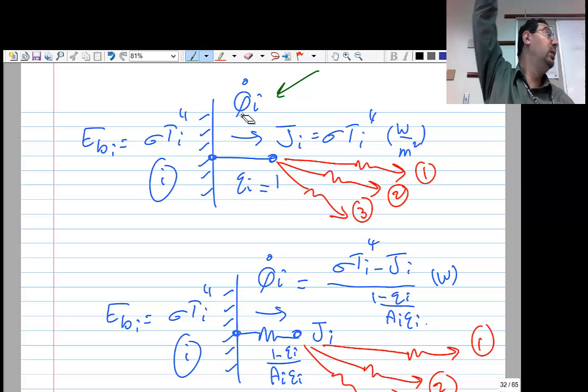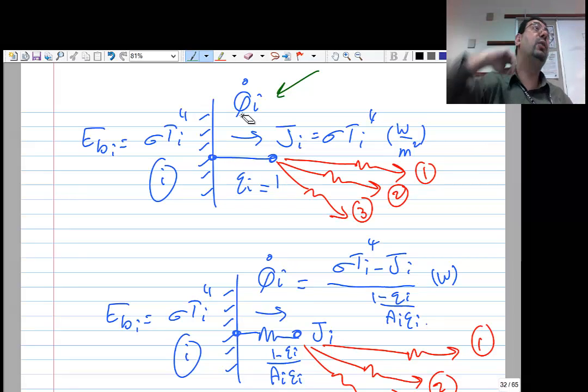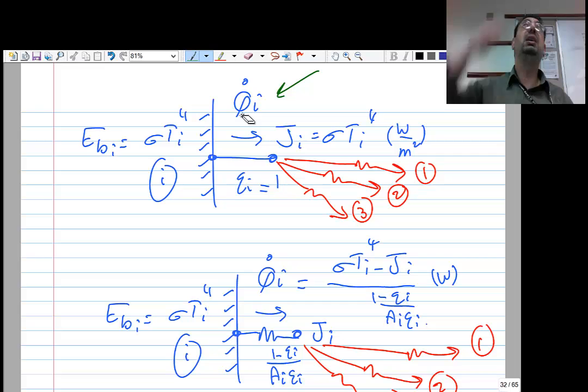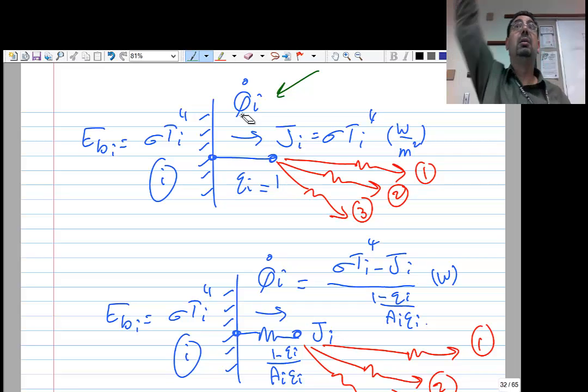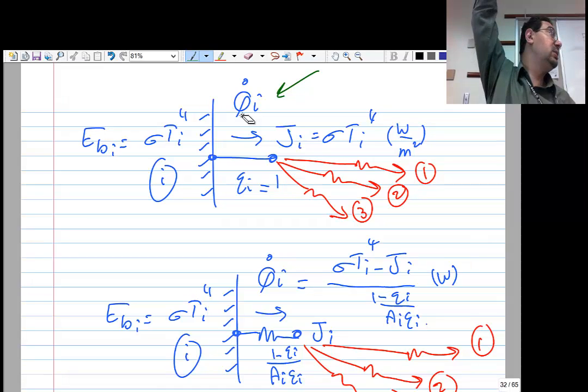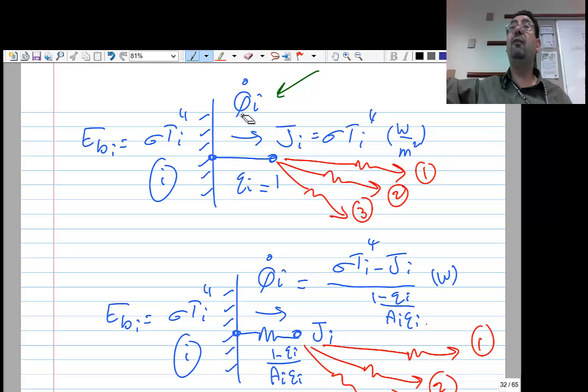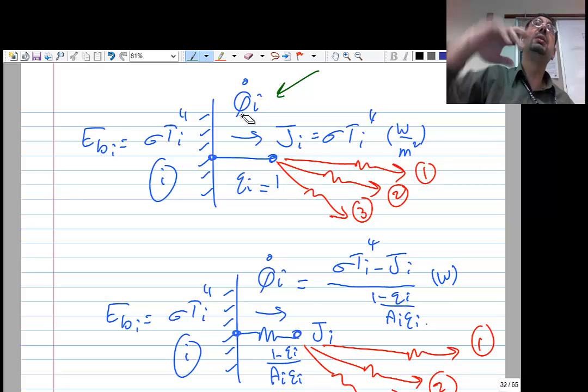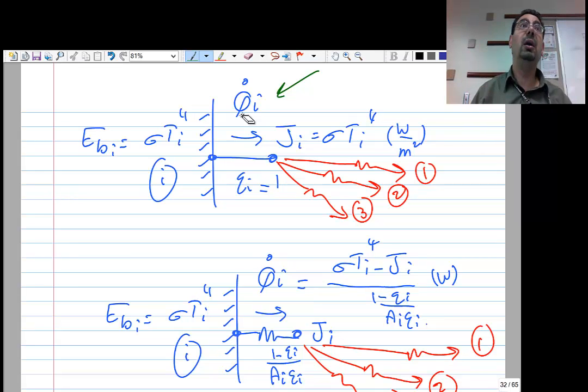That's the view factor of each one of them. The ceiling will get 30%, so it must be that flame to ceiling is 0.3, and the curtain will get 10%, so flame to curtain is 0.1. So we will get the view factor from the tables, and out of that Q we will say QI1 and QI2 and QI3.